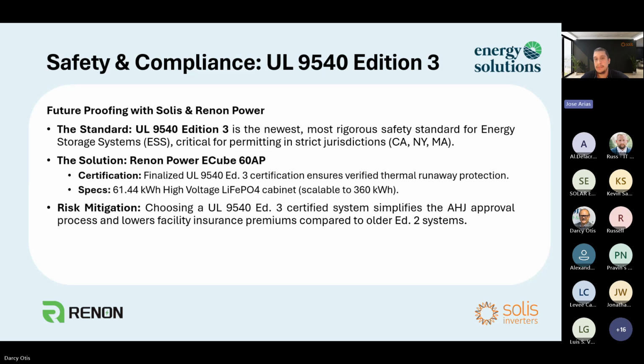And you can parallel inverters if needed, also for adding instant power, surge power capabilities, not only energy storage, either 2 hours, 3 hours, 4 hours backup time frame, but also you can parallel up to 10 inverters, and every inverter having its own battery bank.